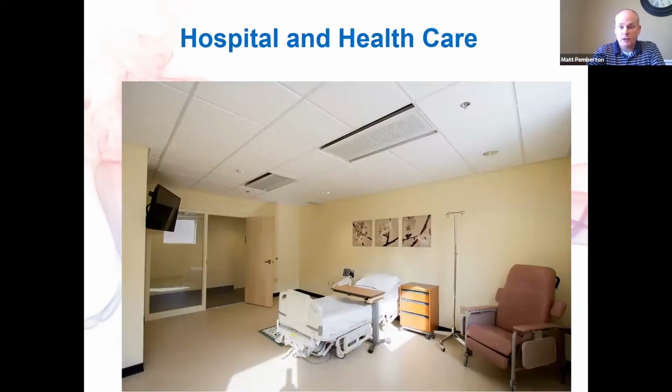We're certainly seeing more in hospital and healthcare, and specifically inside patient rooms. The reason for that is changes to ASHRAE 170 code have now allowed us to use hydronic coil style systems in patient areas if they are designed to be sensible only. Even though we do have chilled beams with drain pans, we sometimes might even pipe the condensate. A large majority of all the projects we're working on are sensible only cooling, so we're talking about a dry coil. That's what has now allowed us to move into the hospital and specifically the patient room area, doing dry coils inside those zones.